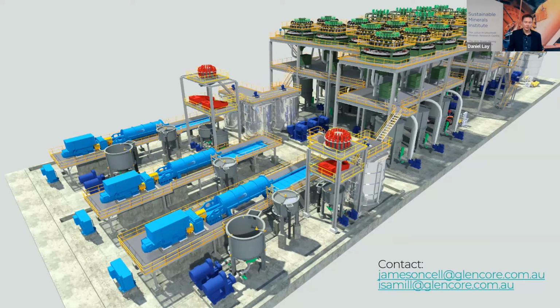In essence, the heart of the Jameson cell is in the downcomer, and nothing changes about the downcomer as you get bigger. There is a step when you go from the 6500 to the 8500, where we went from a 280 mil downcomer to a 500 mil downcomer. That particular scale up has shown itself to be very good. We still get performance on the same grade recovery curve. And essentially what we're looking to do now is just add more downcomers to the same design.